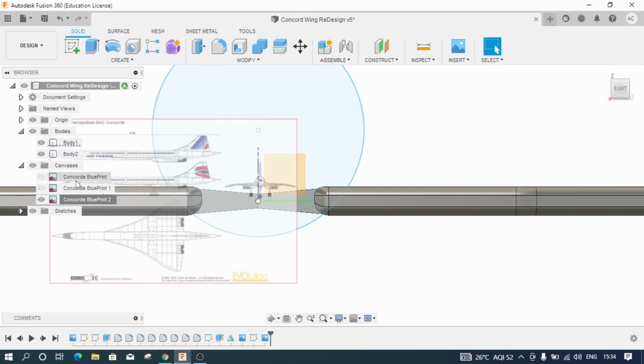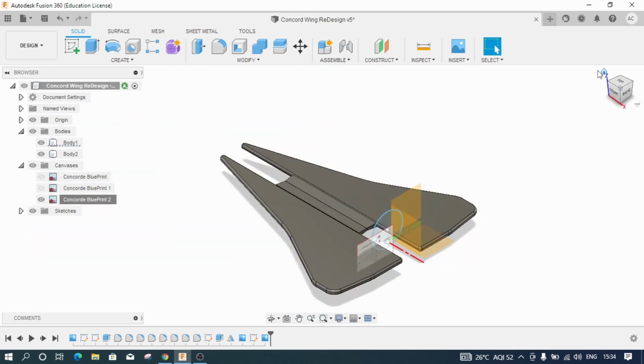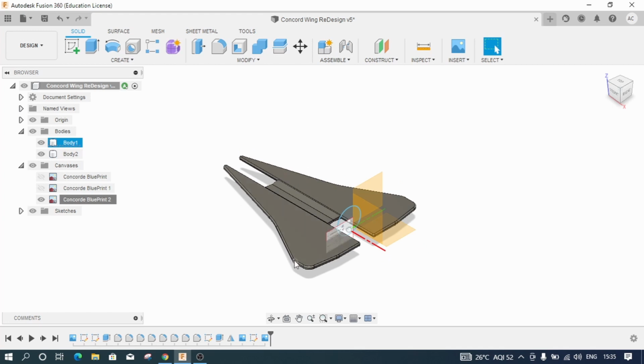and I also want to calibrate this. So how will I calibrate? I don't know what is the exact width of this particular model aircraft. So what I'll do, because we have already modeled these wings as per the image and we have calibrated it according to the length, then automatically the wingspan will also get calibrated. So the width between the tip of the left wing and the tip of the right wing is known as wingspan. These are some of the technical terms which you need to know if you are an aerospace or an aeronautical engineer.